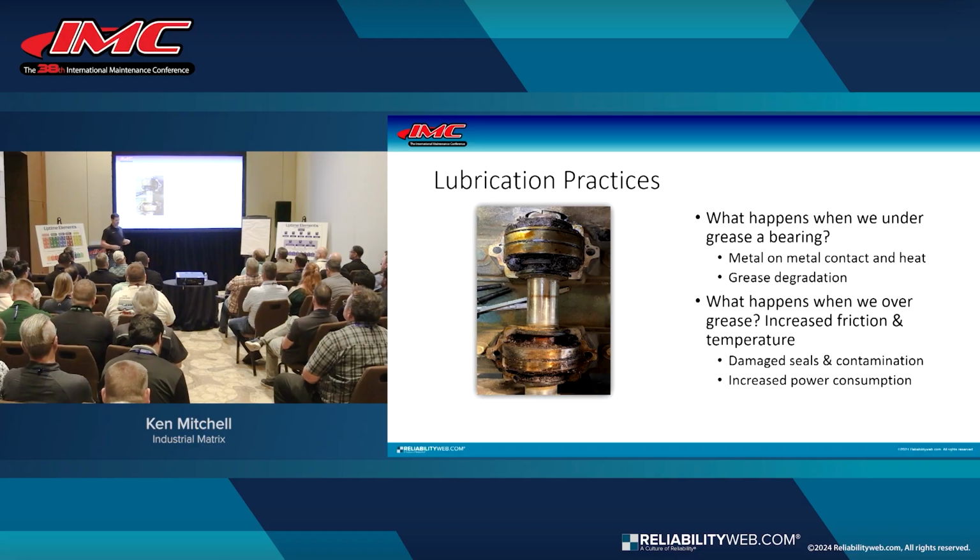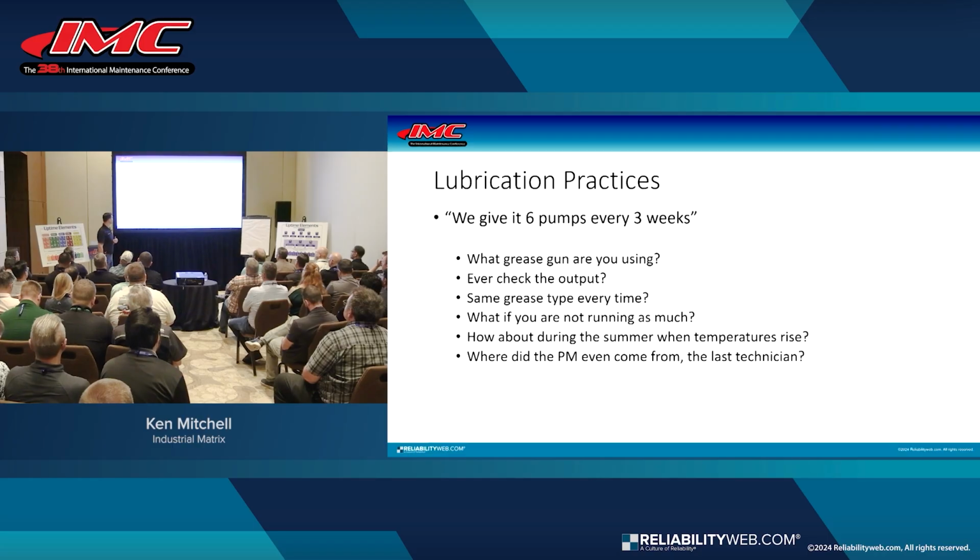The same thing with grease. When we overfill a bearing cavity, that bearing's got to fight a lot harder. We're going to increase our energy consumption, we're going to degrade our seals. Contamination can then become introduced into that bearing as those seals go out, and heat and wear on that bearing. So we want to find that sweet spot of lubrication.